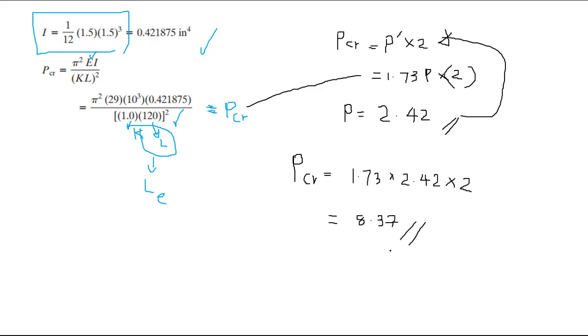Right. So we have calculated the buckling value. This is the P value that can be hung at that point, right? P is this much. If you apply this much, there will be a factor of safety of 2. If you increase it, the factor of safety will not be there. At some point it will reach failure.